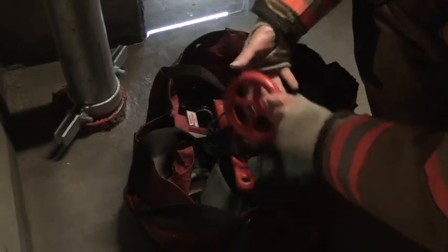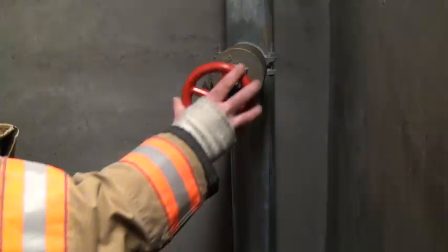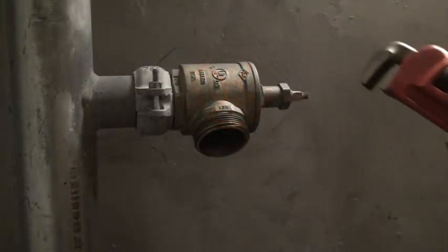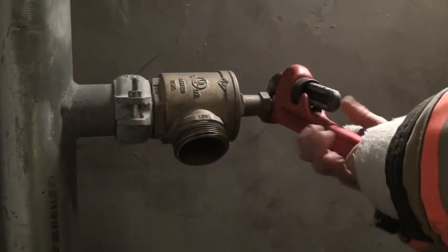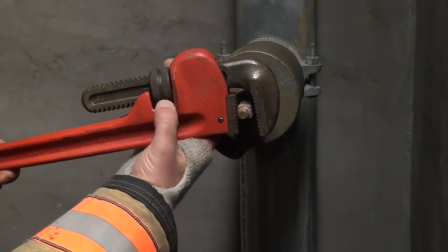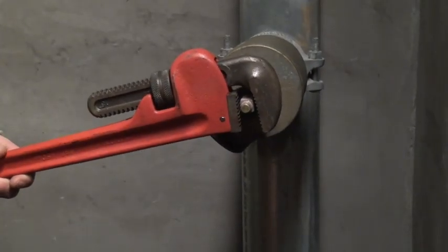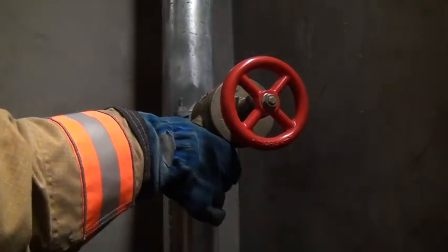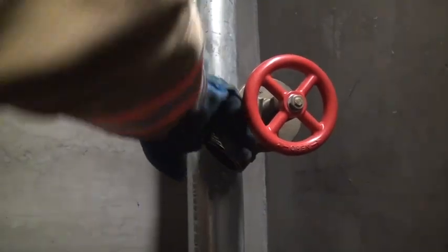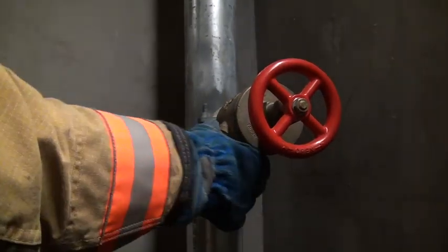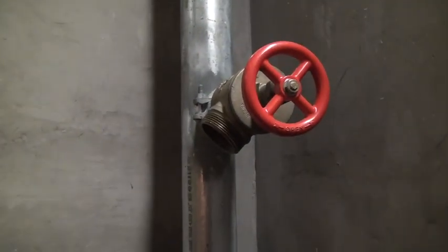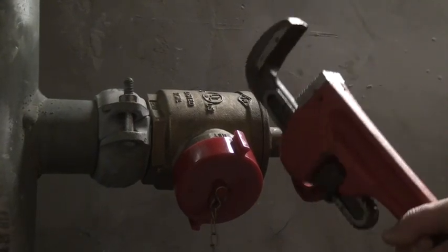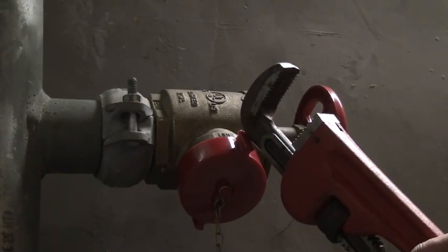A spare wheel may be needed if the wheel is missing. If your bag is not equipped with one, a pipe wrench may be used to open the valve. A pipe wrench can also be used as leverage to assist in opening tight and unmaintained valves. Paint or buildup of other materials on the threads can be wiped off with a gloved hand, or struck with a spanner wrench to knock off the debris. A plastic cap that is stuck can be struck with a spanner wrench and broken.